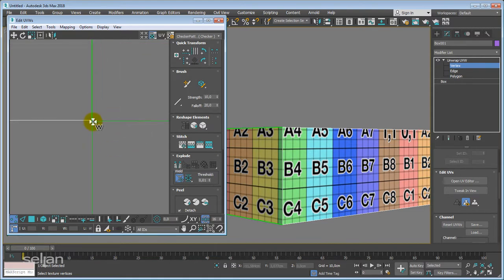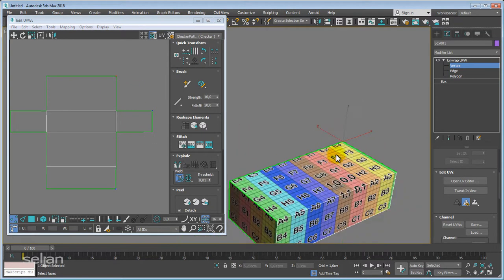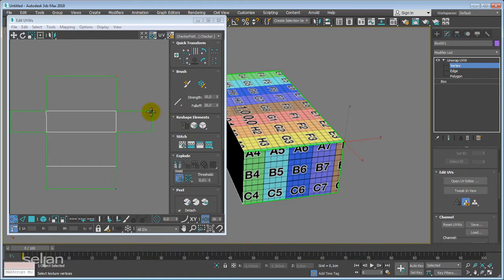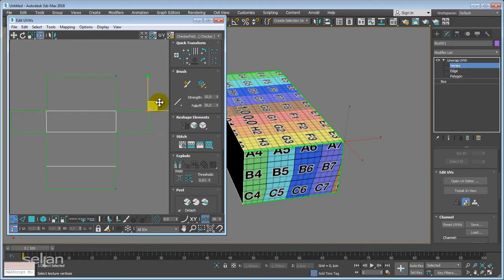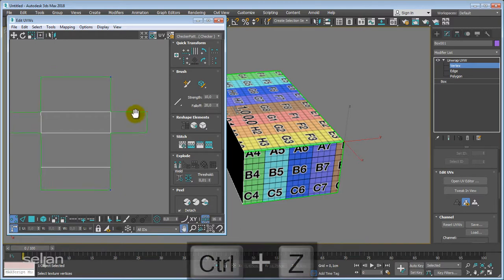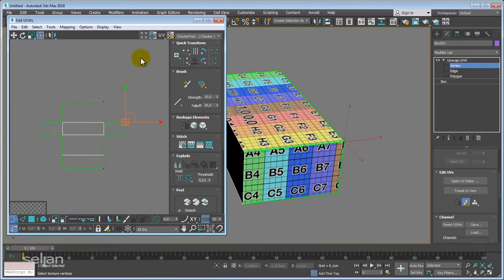All right, and if you are doing good and everything is welded, usually 90% of the situations you have this white edge. Okay, so now white edge, these are opened edges. These two are actually connecting, but this is the point. Actually, this point is belonging to this particular face. So if I move it away, just quickly, can you see what happens? This distorts.